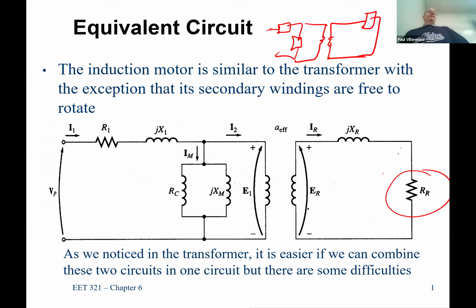That's not shaft output, unless you have a way of saying, here's the resistance, including all those shaft losses too. So if we said it's 100 horsepower, that's the actual mechanical torque that's available. But if we tweak that and add an extra horsepower or two to include friction and windage losses, bearing losses, etc., then we certainly could do that. Because the friction and windage losses are just watts, so we can add resistors for that.